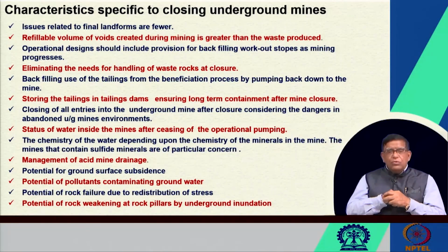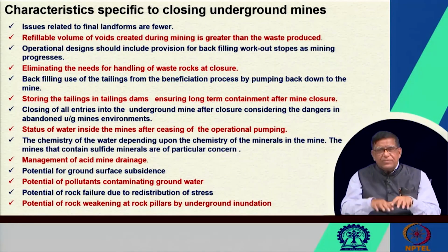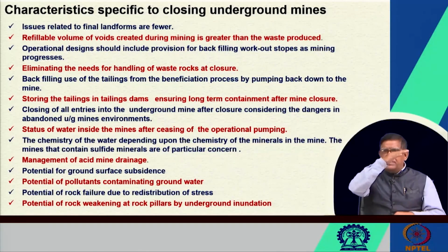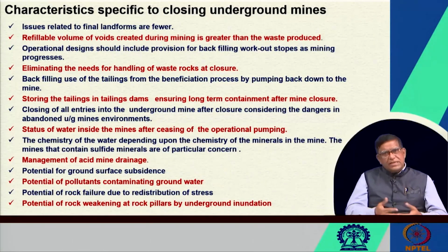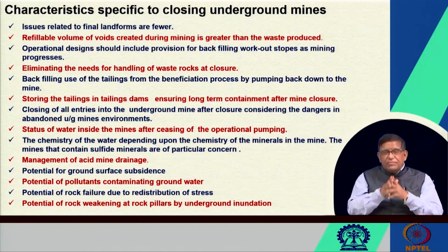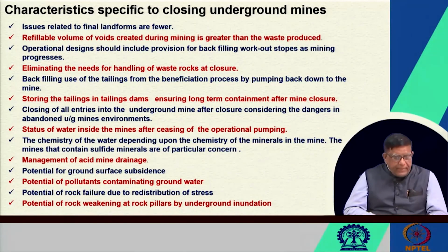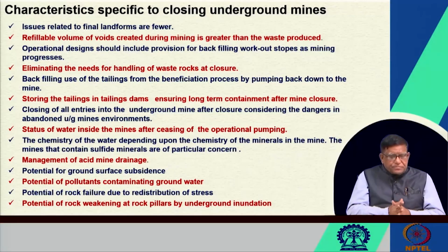Similarly, the ground surface can subside because of the collapse of the void below. If the roof collapses, then there will be subsidence at the surface, and sometimes, if it is agricultural land at the top, because of the subsidence the water holding capacity of that field will be lost, and then the field will dry, the trees and plantations cannot grow properly, and the agricultural yield of such a field may get reduced.